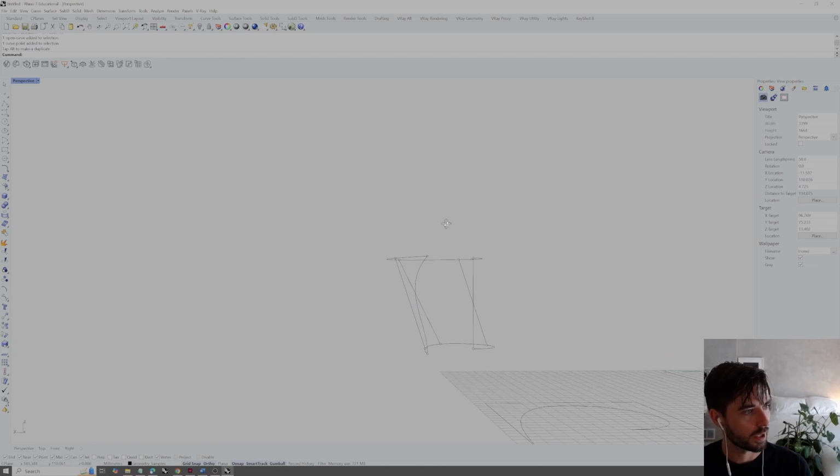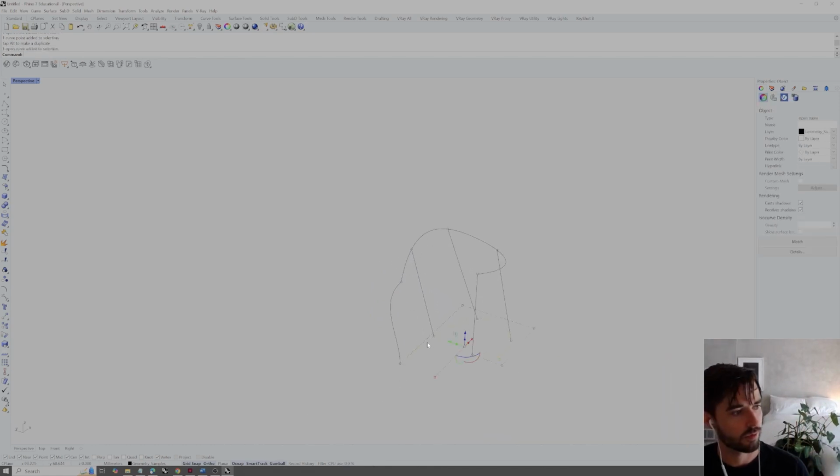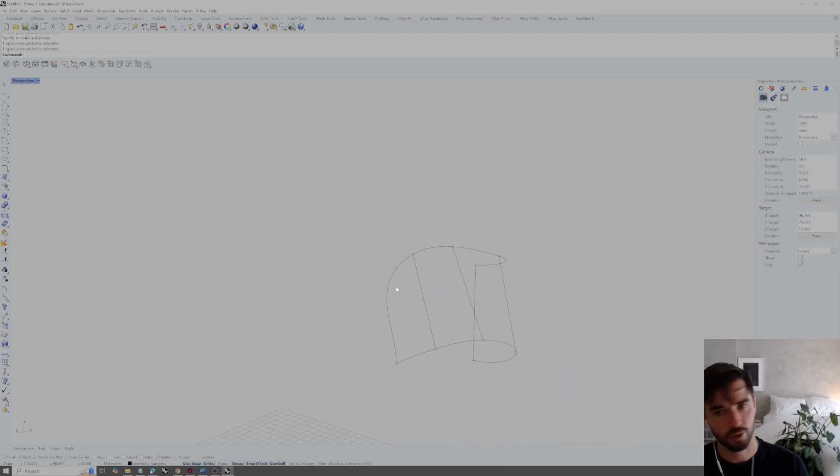So let's say we wanted the curve profile on top connected to the curve profile on the bottom here, but we wanted something like this as a kind of curvilinear set of profiles sweeping along them. Well, we can use the command for sweep, which allows us to take any 2 rail curves like we have at the top and bottom. I'm going to just go ahead and delete these division points that we've drawn out. So 2 rail curves.